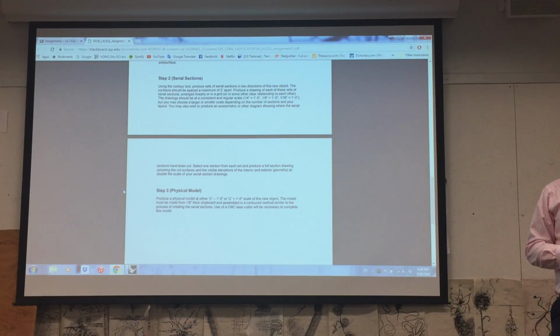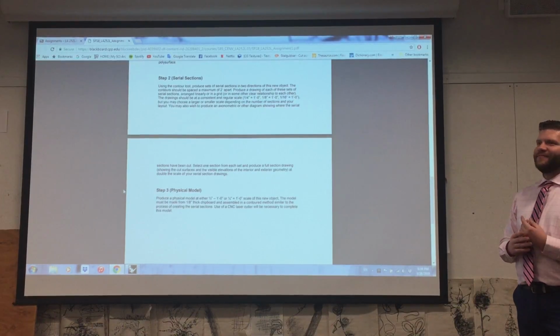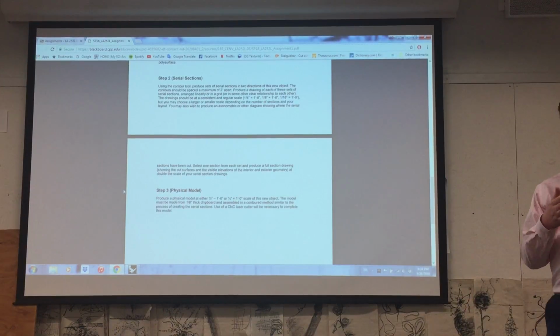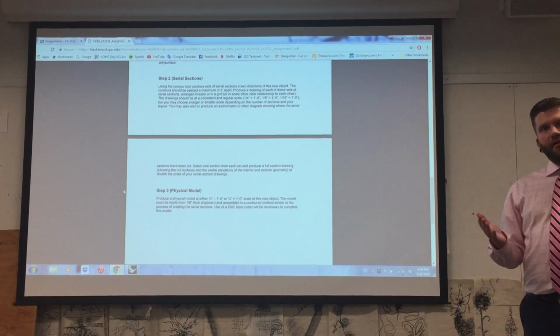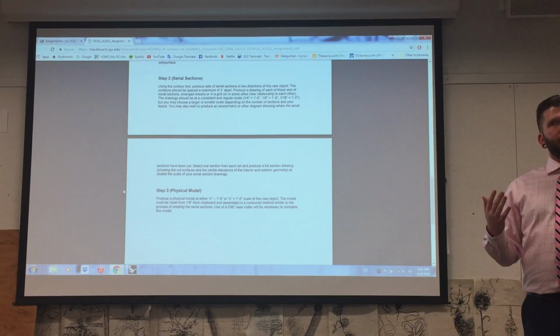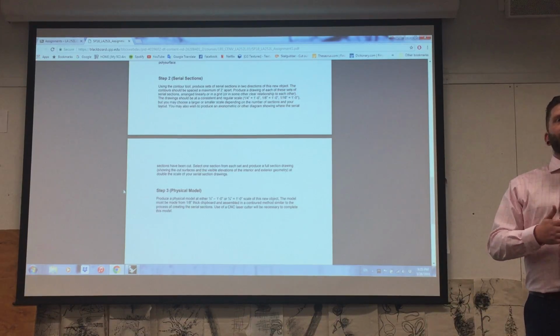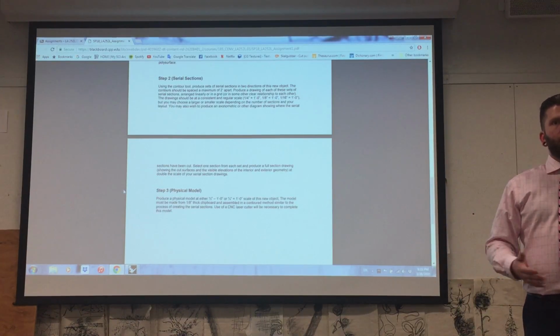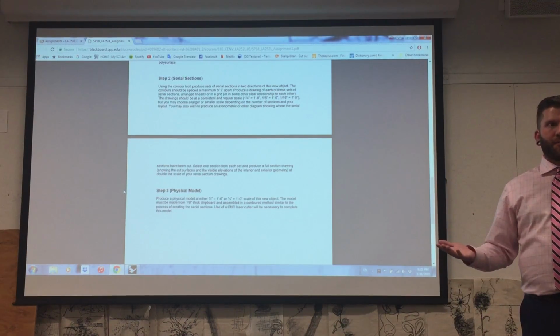Yes. How did you get that answer? Because 1/4 of an inch has nothing to do with scale. Then no. That's the right answer. The reason why I would make contours 1/8 of an inch apart is because the material I'm going to make the model out of is 1/8 of an inch thick. If I were to make it out of 3/16 inch cardboard, which I might change it to, the contours would be 3/16 of an inch apart. If I were to make it out of 1 inch steel, the contours would be 1 inch apart, right?